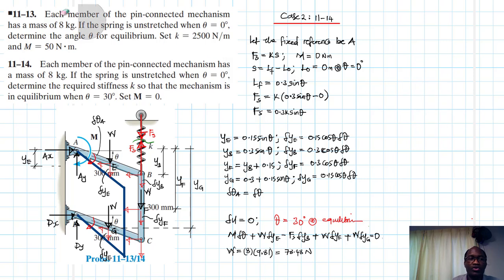All right. So what is virtual work? Virtual work states that for a system like this, an interconnected system of rigid bodies, the total virtual work is equal to 0. And this virtual work can be contributed by the product of translational forces and translational virtual displacement del R. It can also be contributed by the product of a couple moment and rotational virtual displacement. And when we sum up all these virtual works, it is equal to 0.